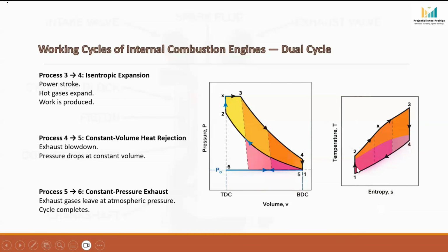So what we know is the vertical lines on this diagram represent isentropic processes. And the rightward movement represents heat addition. And the leftward movement represents heat rejection. And the area under these curves represents the heat transfer in the cycle or work done.